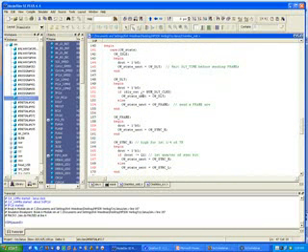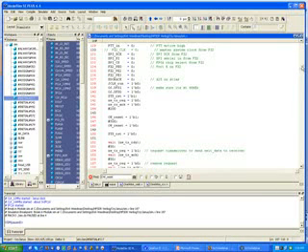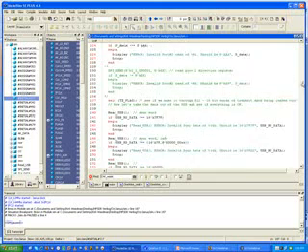So then in the delay state, state 1, we stay in that state as long as this delay count hasn't reached this value. Okay? Delay count on reset also gets cleared, and then it just starts counting. So that's what we see going on right here. After the reset goes away, it starts counting up, and it gets to a value up here of 50. And how did it get to 50? Normally it's a lot longer, but in simulation, I overrode that value in my instantiation.